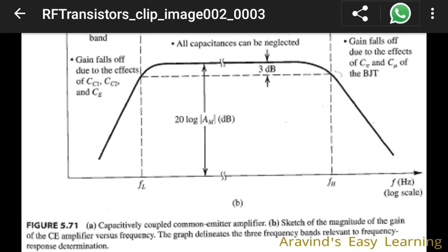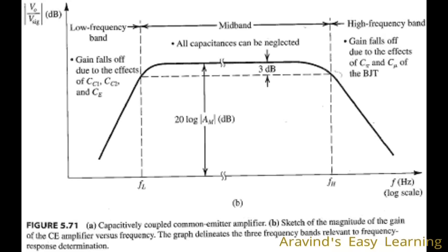It's shown here itself. See, at low frequencies, you know that the formula of capacitive reactance is given by 1 by 2 pi f C. So at low frequency, the frequency is reduced, the denominator is becoming lesser, so the effective reactance is actually increasing.